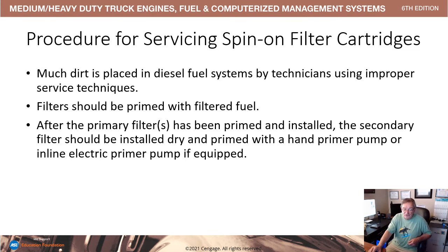Procedures for servicing spin-on filter cartridges. Much dirt is placed in the fuel system by technicians using improper service techniques. Cummins has a clean care kit that is utilized when you open up the fuel system, to make sure that you're utilizing the contact cleaner that they specify and the variety of plastic caps to seal the system as you work.